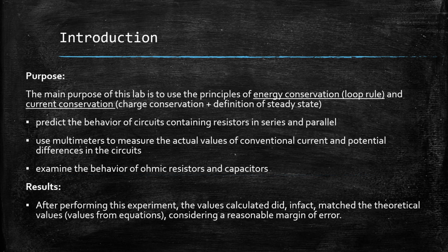The main purpose of this lab is to use the principles of energy conservation or the loop rule, current conservation, charge conservation, and the definition of steady state to predict the behaviors of circuits containing resistors in series and in parallel. Also, to use multimeters to measure the actual values of conventional current and potential differences in circuits, and to examine the behavior of ohmic resistors and capacitors.